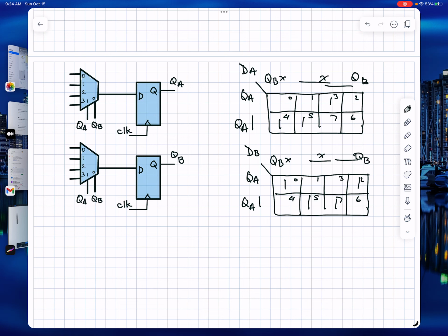Okay, in the second part of the problem, you're asked to use the circuit shown here in this diagram to implement the state diagram. If you take careful note, this circuit diagram uses a Shannon decomposition for inputs dA and dB. So here's dA and here's dB. We talked about a Shannon decomposition back for exam 1 material. The way we get started with that is to reproduce the Karnaugh maps for dA and dB like we had done in the previous step.